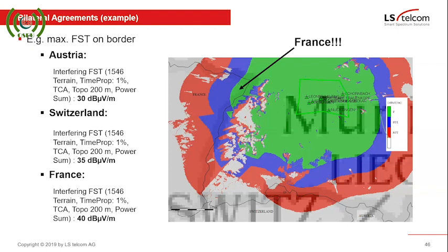I first do one without the new transmitter, and then after the first calculation I will add the other transmitter, and I will see what that increase is. If it's not affecting it by more than 0.2 dB, then it's fine.